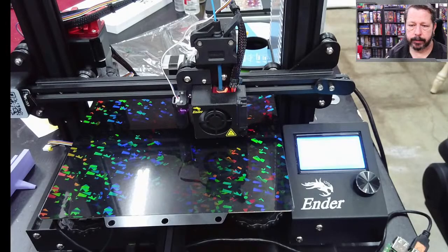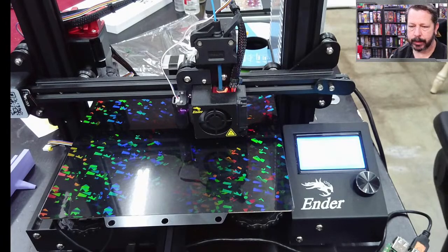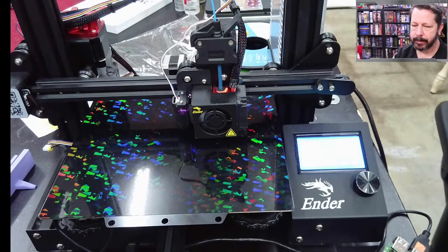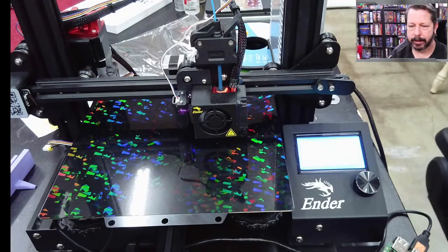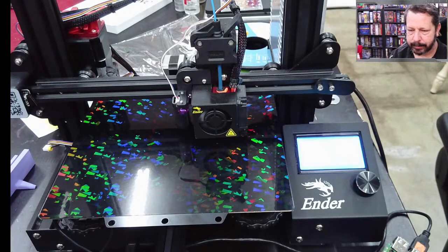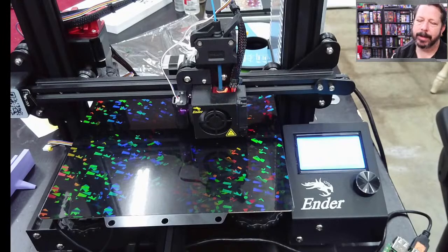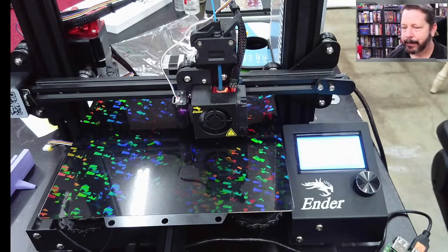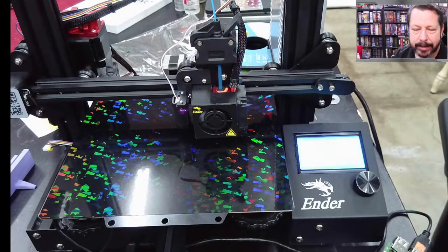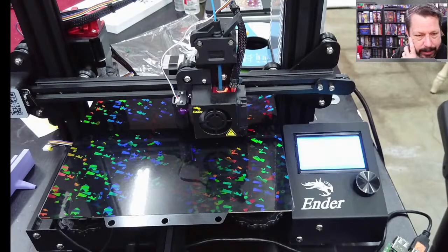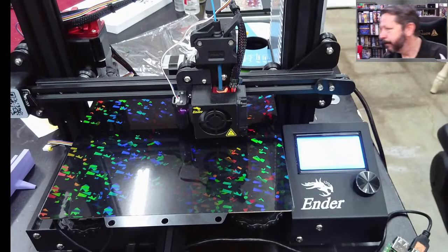Alright, we're at 240. Why did it go back up to 240? I don't know what it's doing. It must have sent another G-code command to get to 240, even though I told it to go to 225. So I don't know what it's trying to do. Now, oh, no. So what it's doing is, in the G-code, in the slicer, I guess, either one, the slicer or the hard firmware for the printer, it wants the bed at 50, which is actually a little cold for PETG.